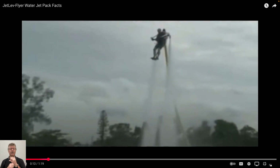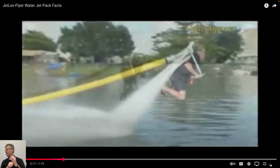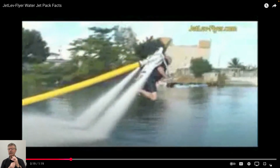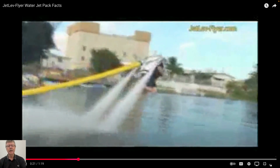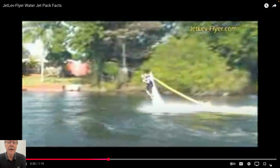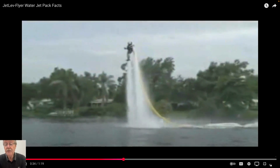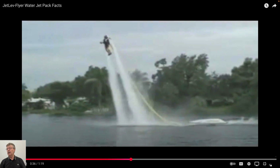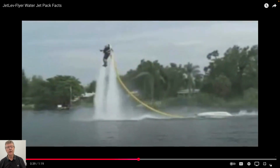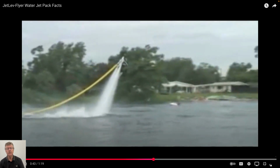We entertained ways to calculate mass rate in minus mass rate out equals mass rate accumulation in static and moving and deforming coordinate systems. And we'll use a bit of that today, maybe, because, of course, we did this calculation with Bernoulli to see what it would take to lift a 100-kilogram person, what kind of flow rate you'd need to do that. And we used Bernoulli to do that.